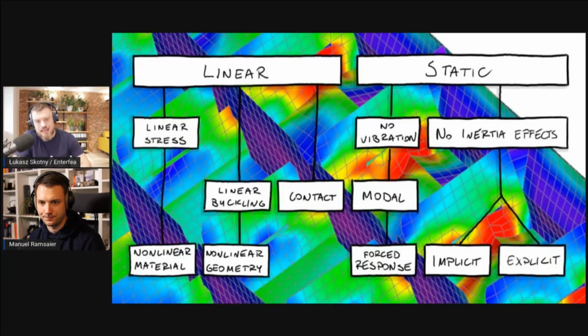And the second one is something that people are rarely aware of, and that would be stability. Because you can destroy something even though the stress did not even get close to what you are willing to accept. Yes. Because if something is very long, very thin, you start to compress it, it will just bend out of shape and everything goes south.